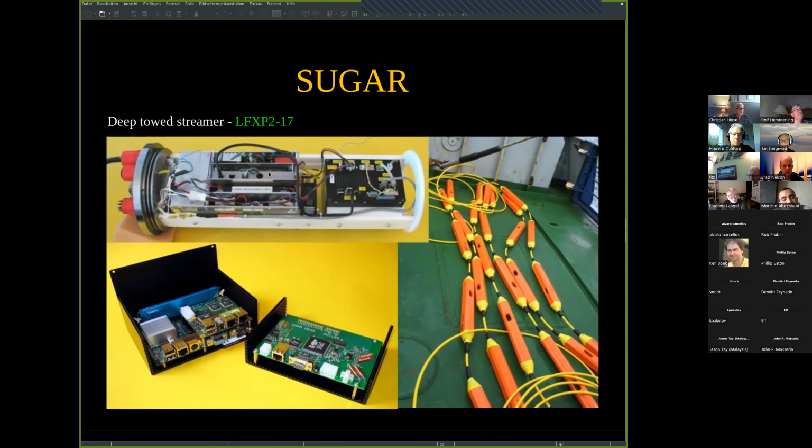observing it. And here, for instance, you see the modem that would receive the TCP/IP signal from the PC here and send it, and this unit here couples these signals into the tow cable, and that bridges the 7 kilometers to the boat. And here in this example, we used a lattice FPGA, the XP2-17, which turned out to be large enough.